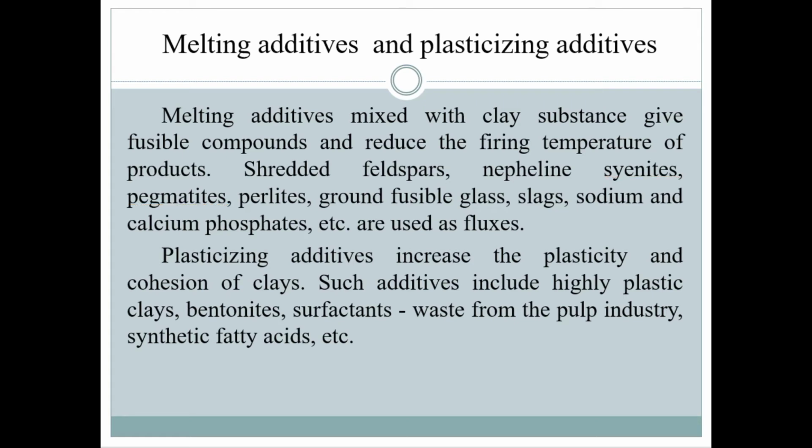Melting additives and plasticizing additives. Melting additives mixed with clay substance give fusible compound and reduce the firing temperature of product. Shredded feldspars, nepheline, cyanites, pegmatites, perlites, ground fusible glass, slag, sodium and calcium phosphates. Additives are used as fluxes.